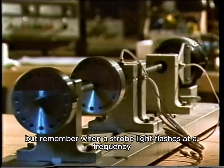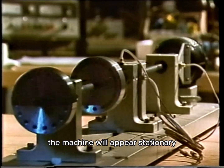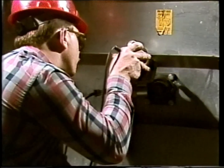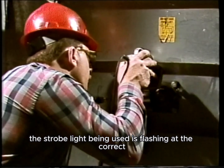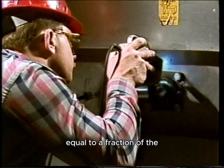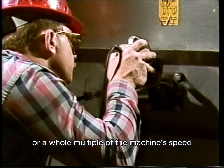But remember, a machine will appear stationary when a strobe light flashes at a frequency equal to the speed of the machine, so you'll have to be careful not to forget that the machine is moving. It's sometimes difficult to tell if the strobe light being used is flashing at the correct speed. The machine can also appear stationary if the strobe flashes at a frequency equal to a fraction of the machine's speed, or a whole multiple of the machine's speed.